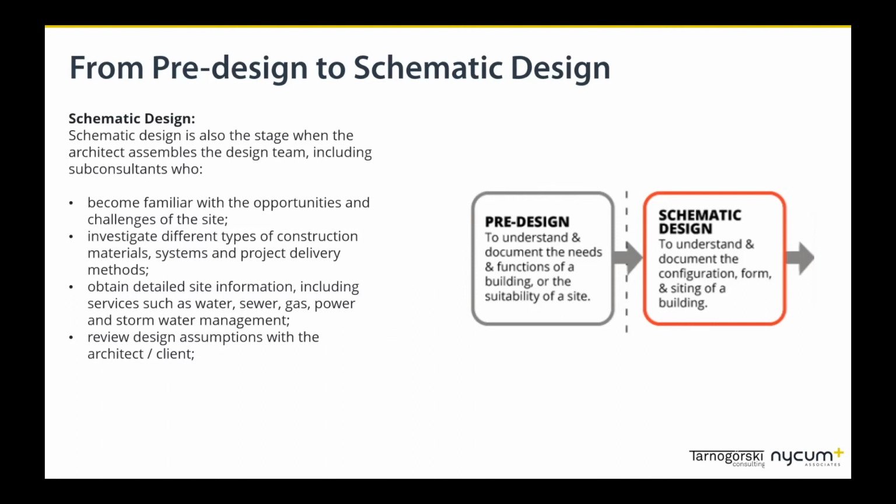Those are the sorts of things that you start to parse through in schematic design. And you either say, well, that's a constraint that I'm not going to be able to overcome, or you say, well, let's say the site's too high, or the water line on the main street is too high. You say, well, we're not going to do a fill or put the project higher up. We'll just get a pump. Those are the sorts of conclusions that you come to, problems that you run into, and solutions that you find with your consultant teams. And then you just review, and you review, and you review.